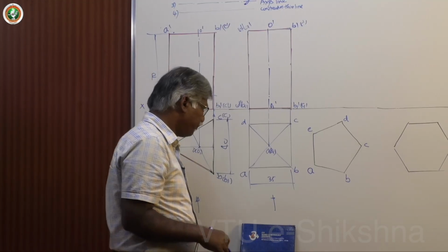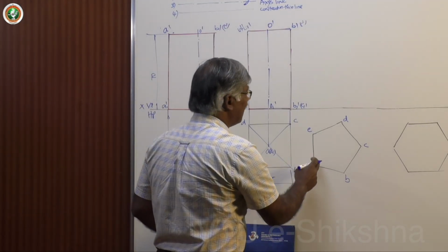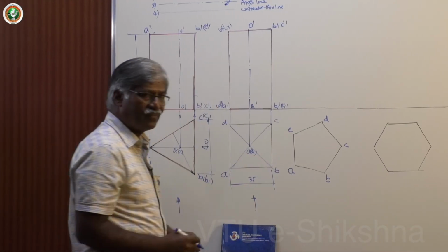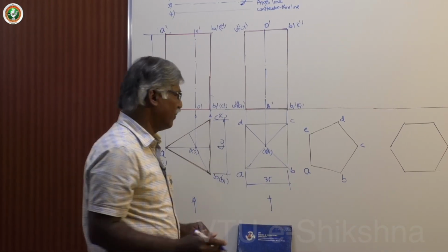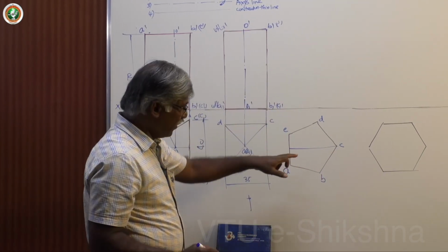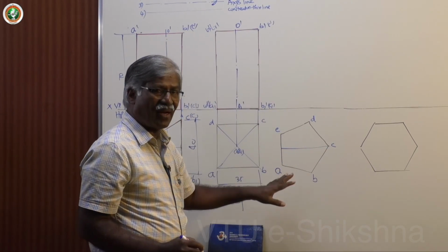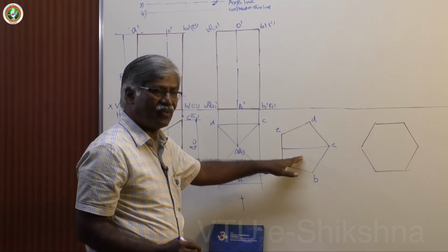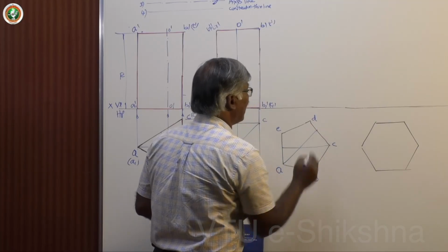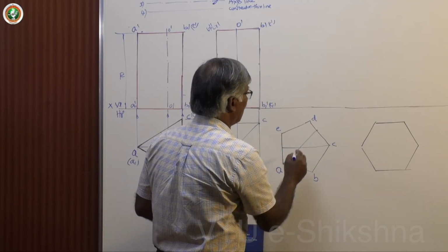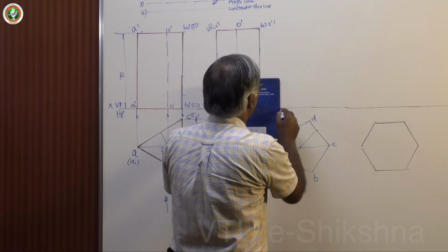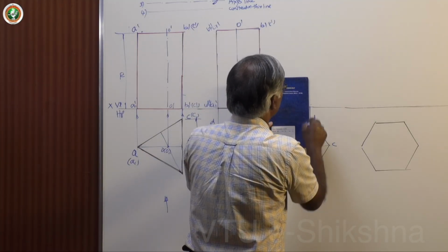Okay. Now, having these points named, how to identify the center? Normally for all solids, center must be identified. Perpendicular bisectors. Draw by default one perpendicular bisector always parallel to the XY line. It's better, one of the perpendicular bisectors. And this one, any one you take midpoint and then draw. Then the projection should be identified for all the corners.